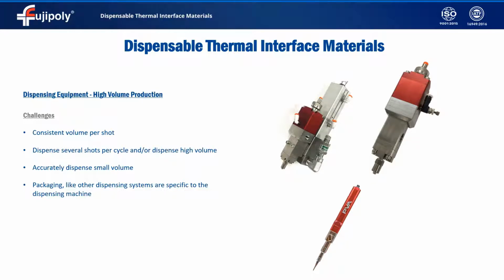For smaller shots or if a more consistent volume-based dispensing amount is required, then there are lower pressure valves that work with cartridge systems. There are positive displacement and positive cavity types, which can more accurately dispense material while sacrificing maximum volume and dispensing rate.